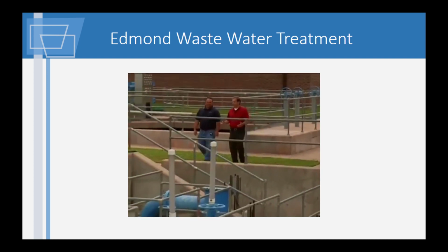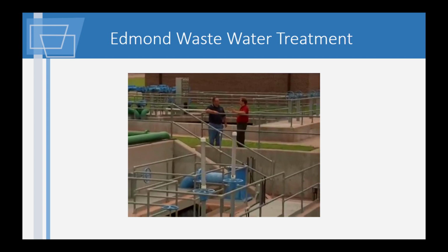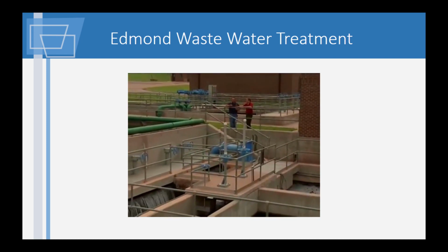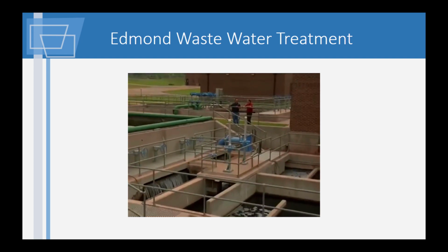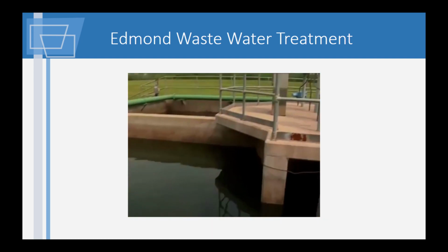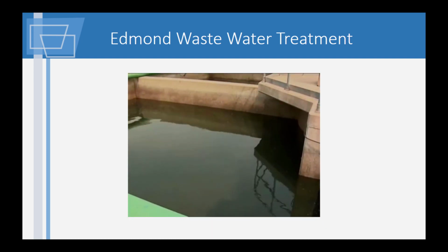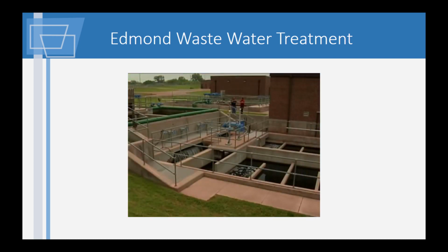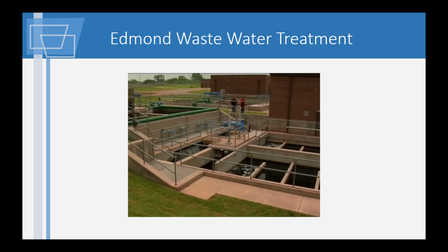Okay, Chris, I guess we're at the last phase of the water cleanup. We've just finished with that part. Now we're going into here. What is this? So from the clarifiers, we're heading into sand filters, which is just polishing fine particles that may have escaped the clarifier and screening them out, basically. What's the filter? There's 30 inches of sand in there before it can release through the bottom. It's all gravity draining down through the sand. So the sand is a natural filter, and gravity pushes the water down and it comes out into here. Let's go take a look down in here.